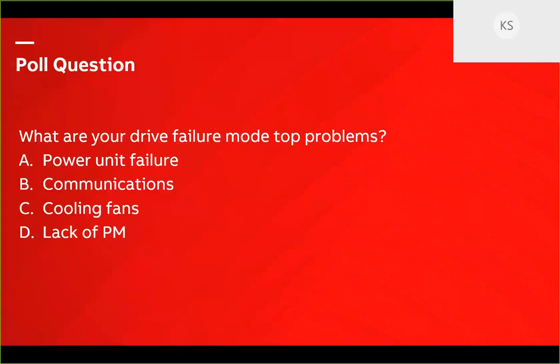And I remember a cooling fan incident from when we'd turned this on in the digital age. It was a new installation, and the temperature was overheating, and everyone said that has to be a faulty sensor, these are brand new drive units. Well, somebody had put a notebook over the exhaust fan, and it was heating up. We sent a guy out, and we actually changed the geometry of the cooling fan exhaust.